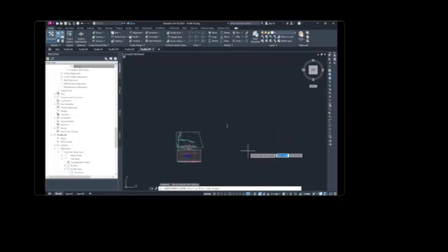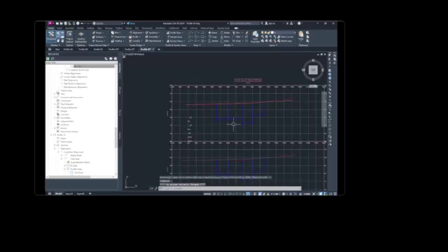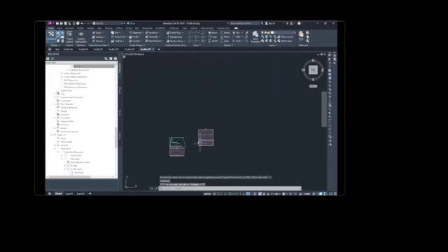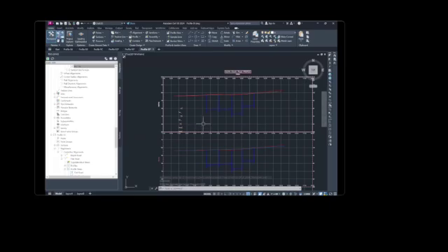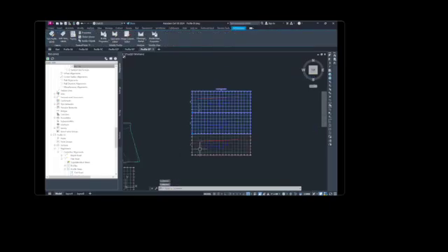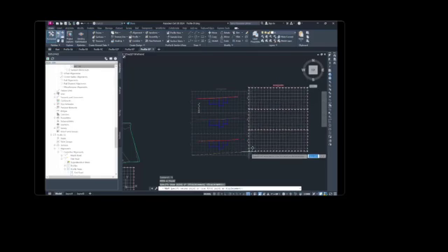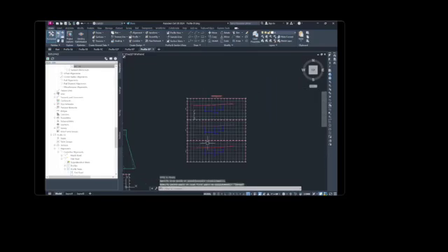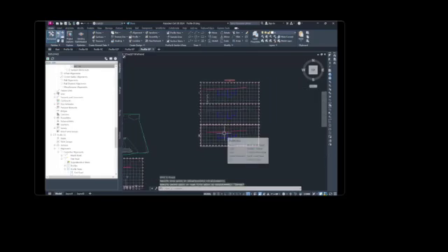We're gonna pan to the clear area at the right of the surface. Click to place the profile views. There we go, they're there, as you can see. We'll move them a bit. These are the stacked profile views.